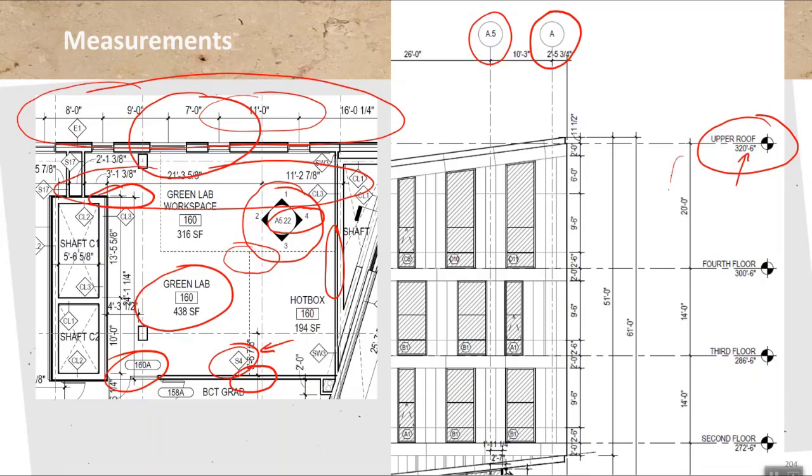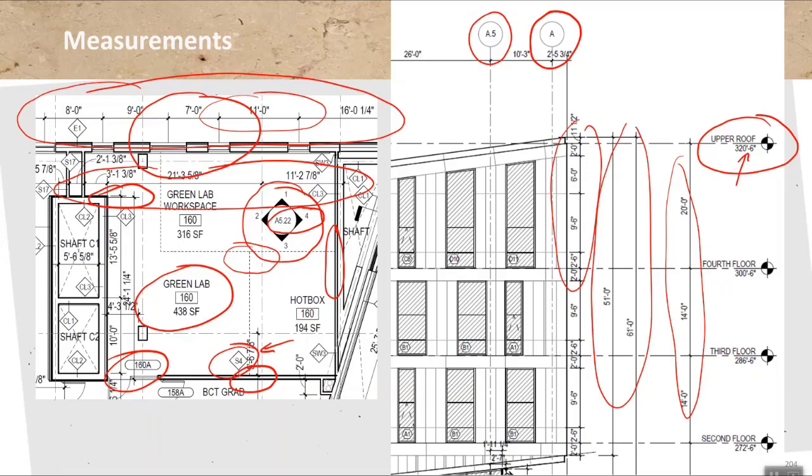You see another chain of dimensions here, and then of course this overall dimension, and then the facade dimensions. So very often you have multiple dimension chains and overall dimensions side by side, and of course you don't want to clutter up a plan too much, but you also want to provide enough information to understand what you need to build if you're the plan author, and of course as a plan reader you want to get as much information as possible.